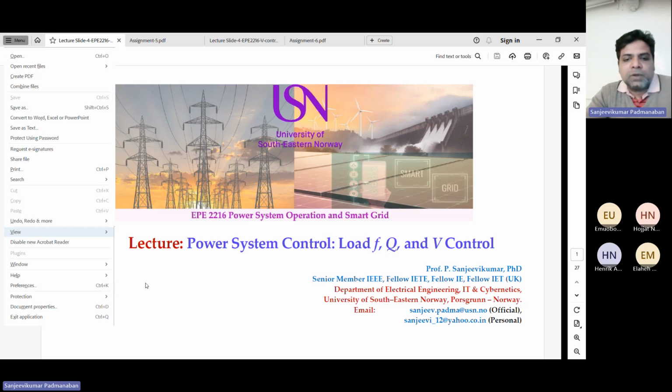So, to understand the system better, we keep a term called delta F, which is a change in frequency. Usually these changes in frequency are sensed by sensors available in the grid system or power systems. By using voltage sensors and current sensors, we get the feedback of voltage and current. Then we calculate what the frequency is.